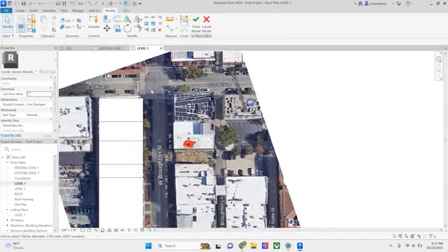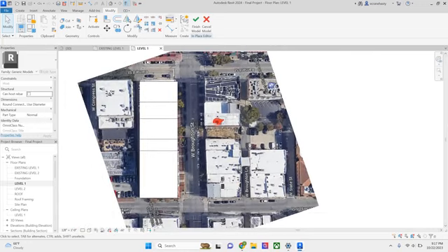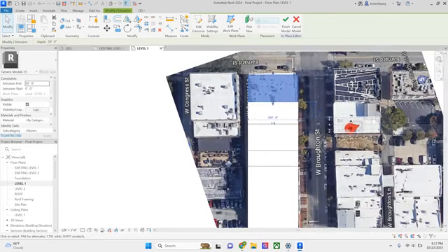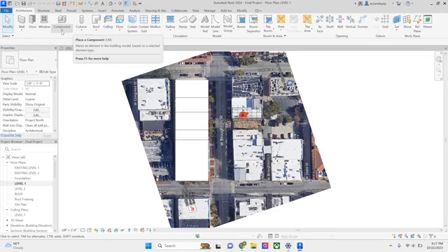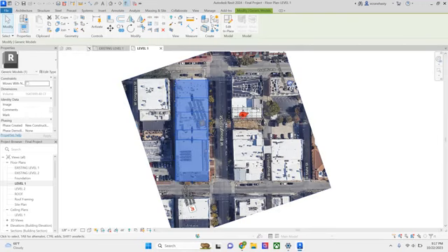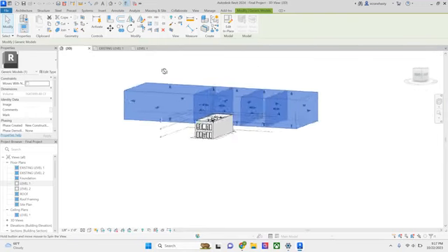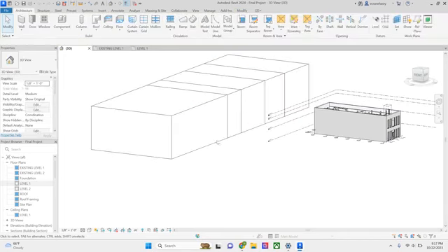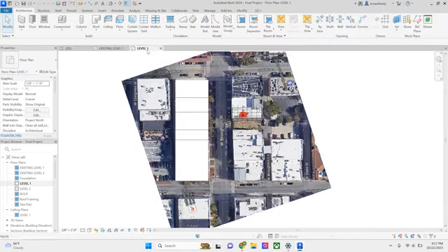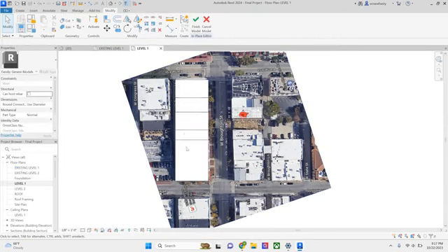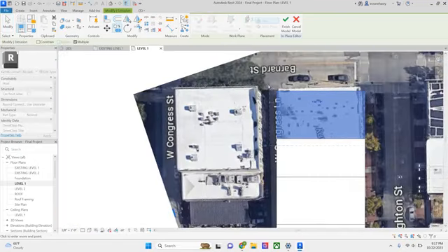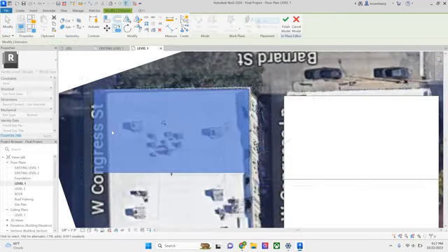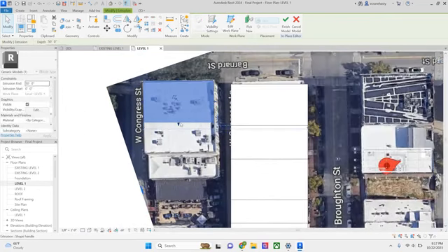So I typically just kind of start with either the streetscape or I'll start with the surrounding buildings. I will come over here to architecture, use my generic model in place for that. So that's how I've done most of these buildings, which all currently are at the same height. I've not specified any special height to them. But I will. So let's just start modeling, and y'all can speed through this if you want to. It's really just kind of for your benefit of how I do this.